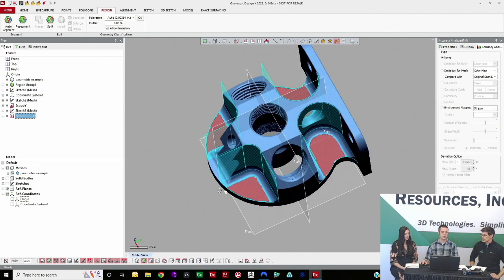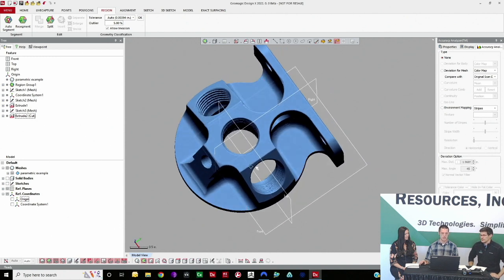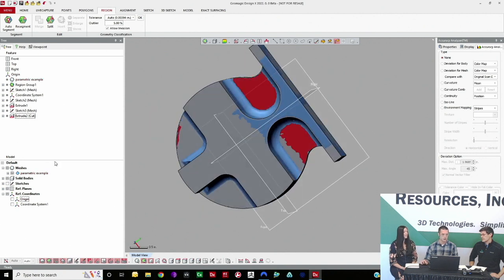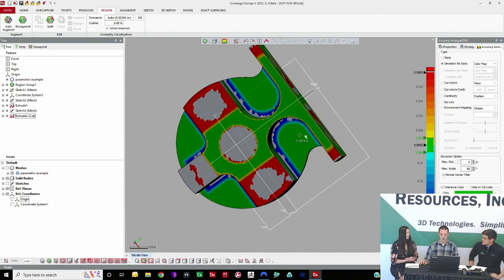You can also have it trim with a region fit surface, which means that it assumes the curvature and shape of that region as well, assuming that it's not too crazy of a shape. Like if that face had a slightly concave shape, I could trim with region fit surface, and it would assume that concave shape automatically. So you wouldn't have to create that custom surface. Your cutting tool does that for you. Yep, right. That's cool. It automatically assumes the shape, so you wouldn't have to fit a surface and then cut before you did a Boolean operation.